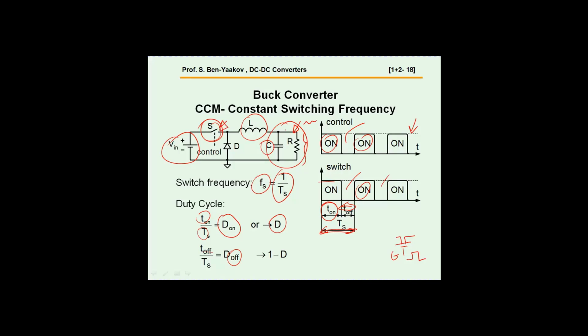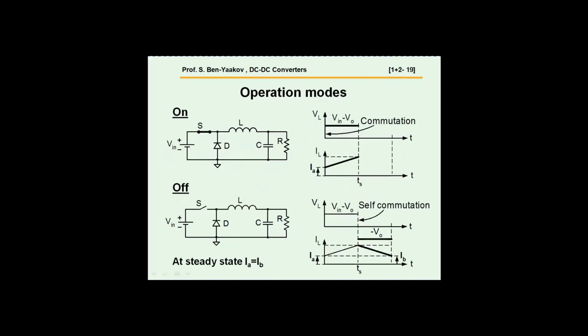The inductor is turning on and off. And what is happening here is that if you look at this point, what you'll see is that at one time the inductor is connected to the input voltage, and then it is sort of left alone because the switch is open, sort of the current is interrupted. So here we see this operation. We see that during on time, the V-in is connected to the inductor.